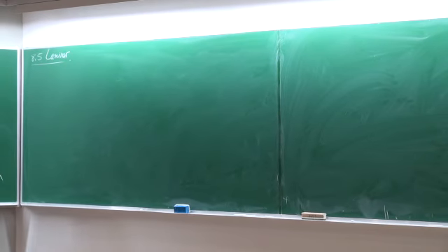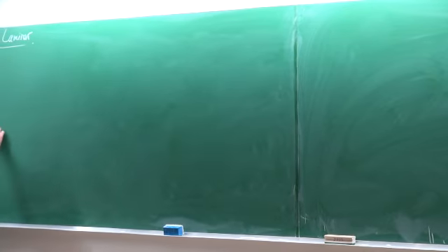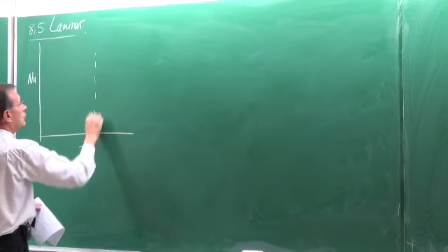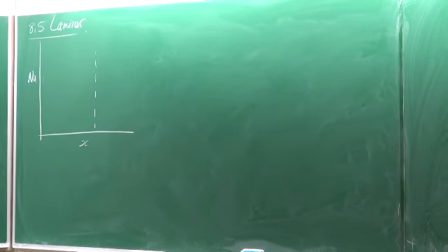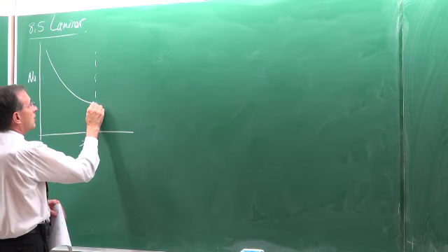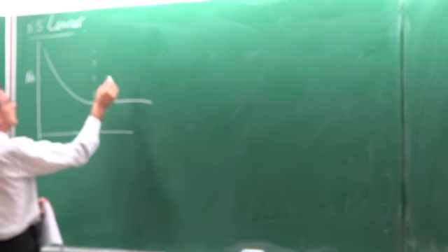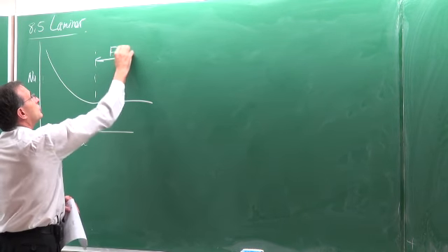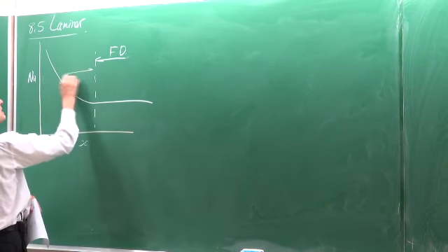Now the thing that is important with laminar flow in tubes is that this is the Nusselt number as a function of x. We did a lot about it. Then we know that we will have a behavior like that. This is the developing flow, and that is fully developed. So that's fully developed, and that is the developing part.